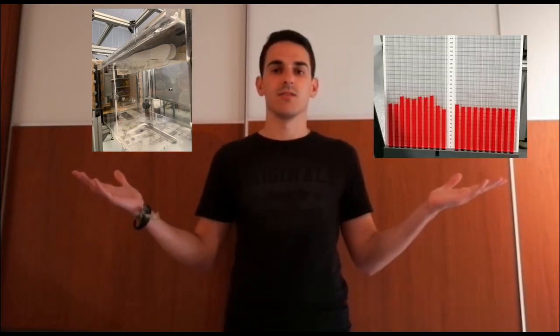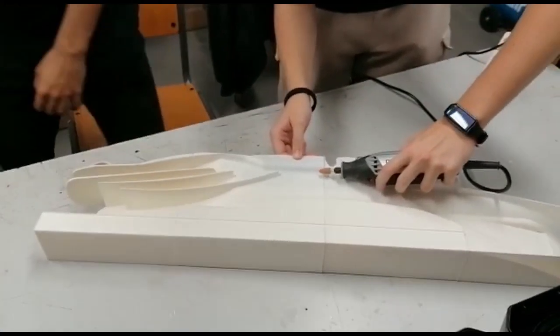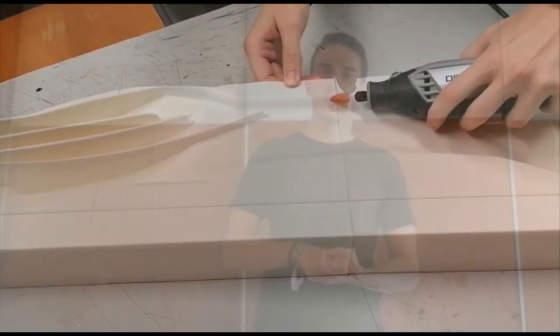We learned to implement the different knowledge acquired in the lab sessions, such as measuring in a wind tunnel or reading the values from a manometric table. We also learned how the devil is in the details, as we needed to smooth the surface of a 3D print with a Dremel, as we know that any imperfection could affect the final results. I could give you 33 more reasons of real-life knowledge that we acquired. Nevertheless, the important aspect is that the desired effect was observed, and we can only imagine the magnitude of downforce that an actual Formula 1 car could achieve at higher speeds.